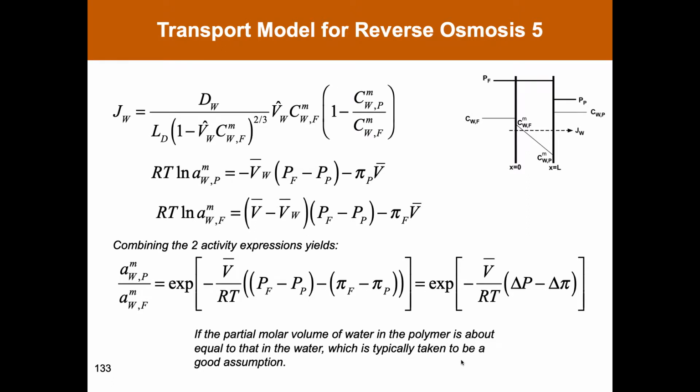We combine the flux model with now our expression for the thermodynamic activity of the solvent in the permeate and feed solutions. What we're headed for is to relate this term to the thermodynamic activity terms, and ultimately to the terms that are over here, because it's the pressure differences and the osmotic pressure of the solute concentrations in the solutions that one can actually measure.